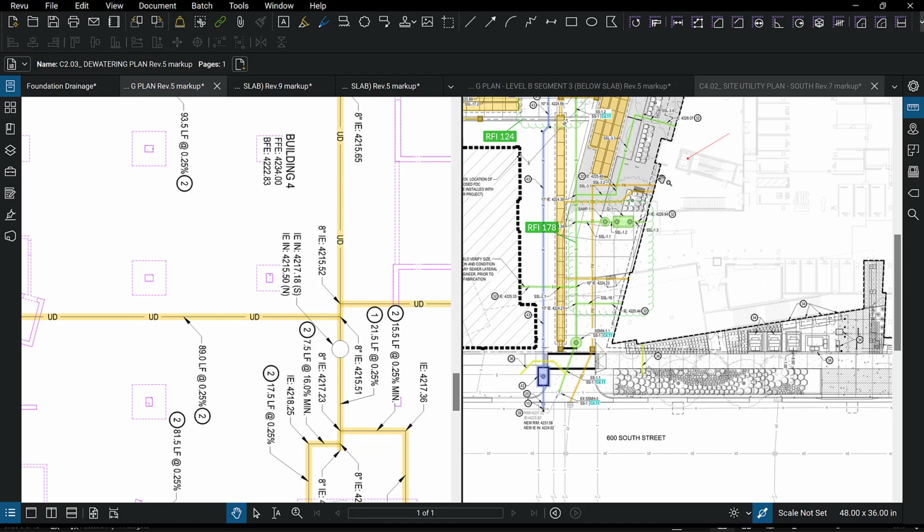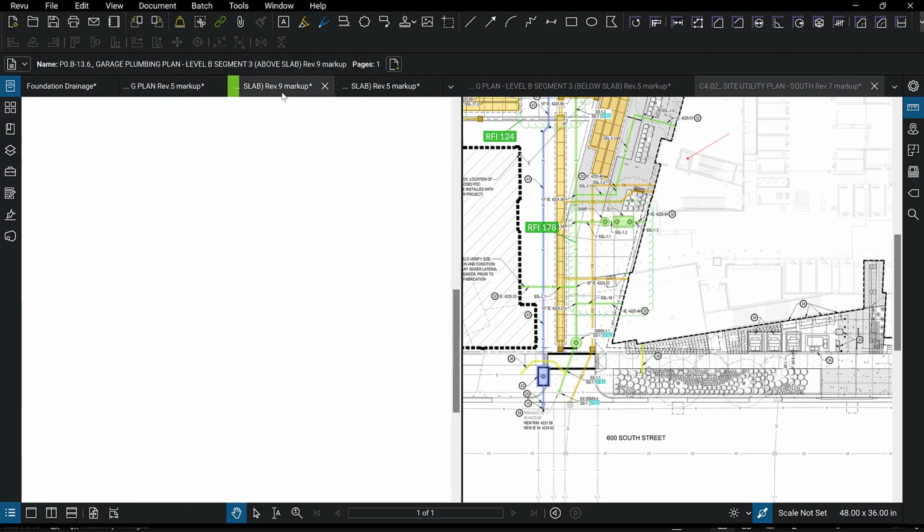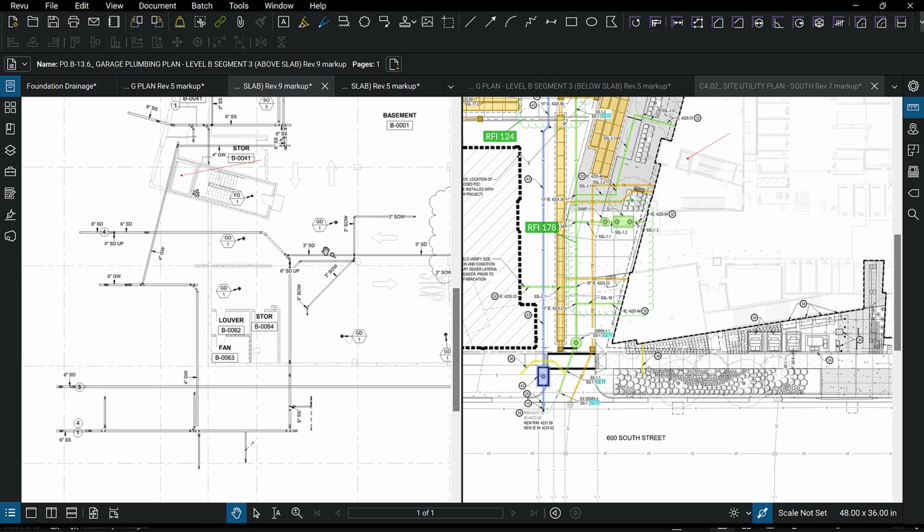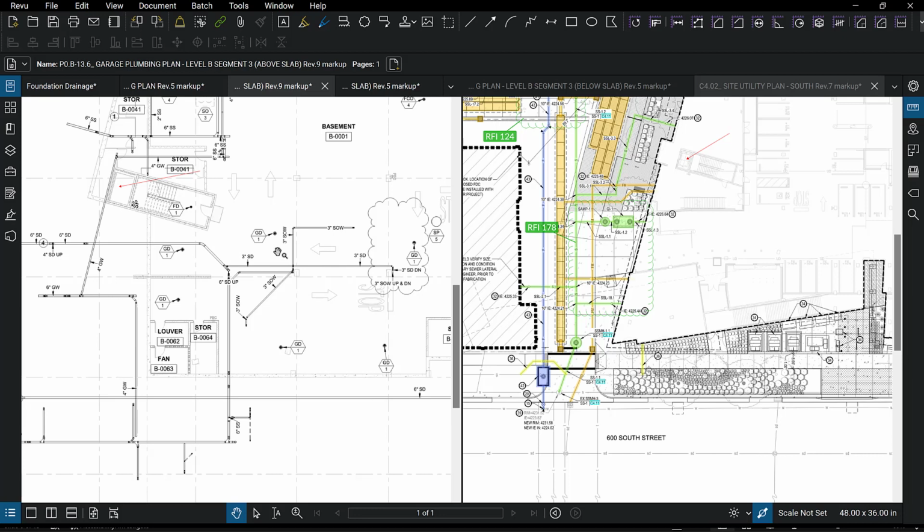Then if we follow the plumbing drawings, which we were just sort of looking at, the plumbing drawings are taking it, and they don't have it drawn correctly. It should come out of this point right here. And it should come out separate, like over here like that, and tie into this forced main right here and come over to here.